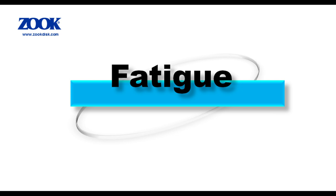Why do rupture disks fatigue? Well, the reason is that they're solid-state devices with no moving parts. As such, by design, they have no built-in safety margin. This is at the same time both a blessing and a curse, as the lack of safety margin is what makes a rupture disk fail-safe, but it's also what gives a disk a limited service life.